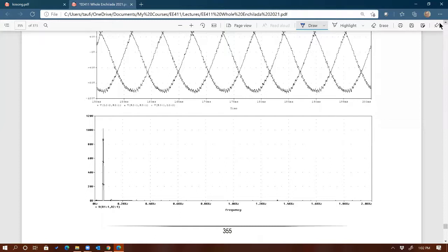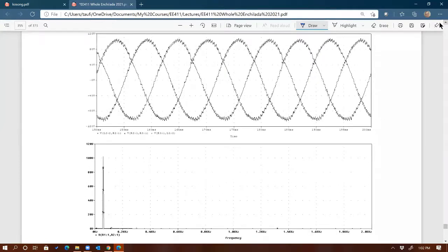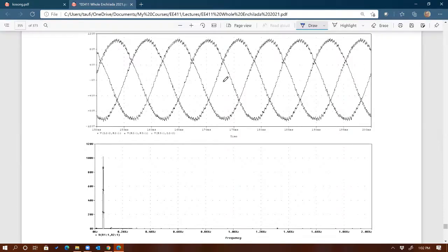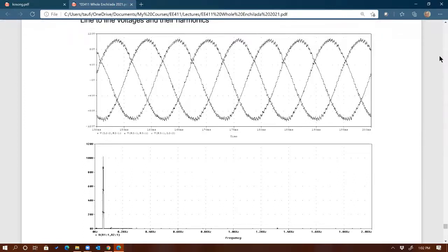Any questions on this? I had a question. Yeah. Is the general advantage of this three-phase method versus the previous one that you get cleaner output because the frequency you're introducing is way further out? And then the disadvantage is the higher switching frequency, which causes increased switching losses. Is that kind of the trade-off?